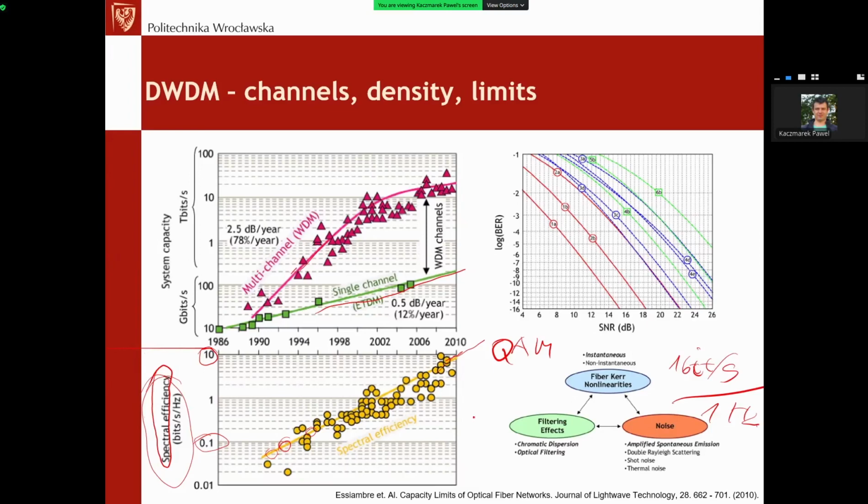Additionally, we can code information not with zeros and ones, but we can use, for example, 4-level amplitude modulation in such a system. So we'll have 4-level modulation and additionally 4-level phase modulation. So one time slot for such a modulated signal will in fact code 4 bits of information. So it will give us, in some approximation, a spectral efficiency equal to 4 bits per 1 hertz of the bandwidth, and so on.